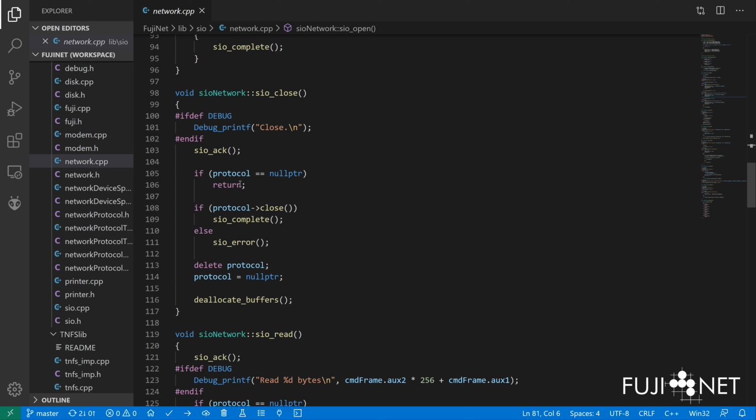Conversely, with close, we try to do any housekeeping that we need to do. And in each one of these, it's important, especially because this is production firmware, we need to program defensively because we're using pointers for dynamic allocations of protocols, and we need to protect against null pointer errors. Boom, just go back if it's not there.